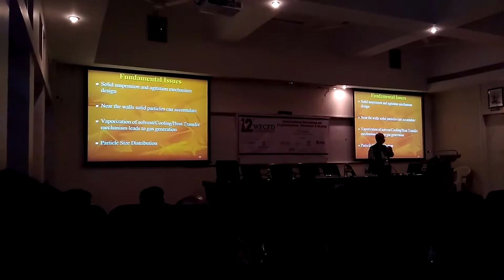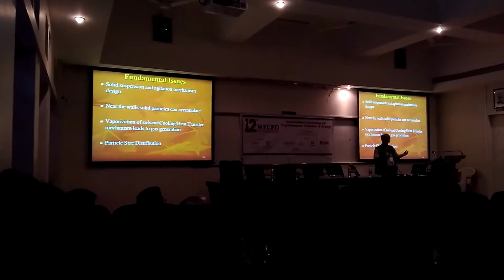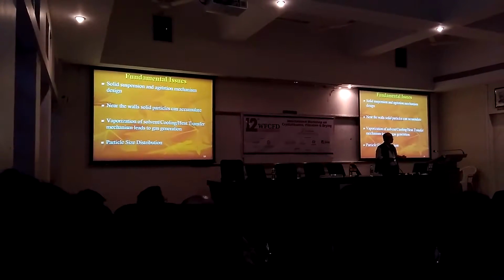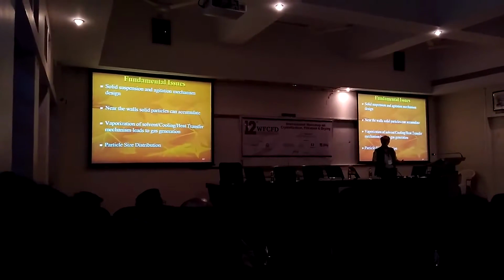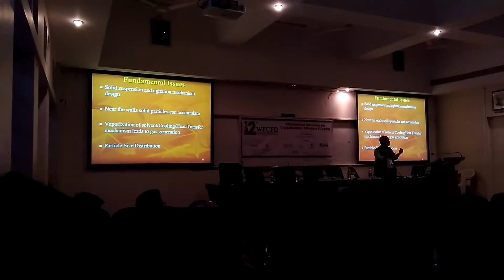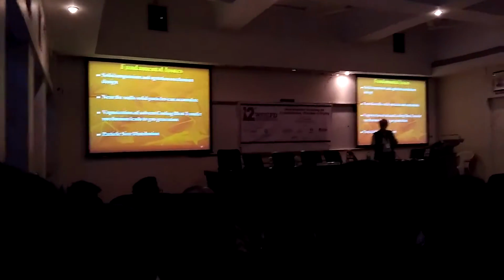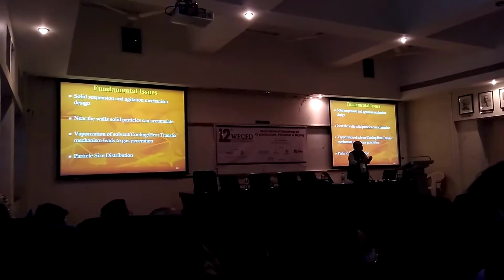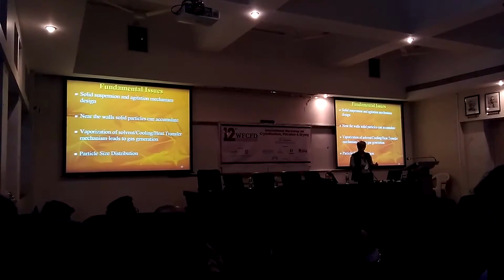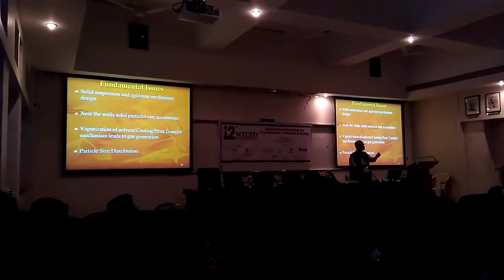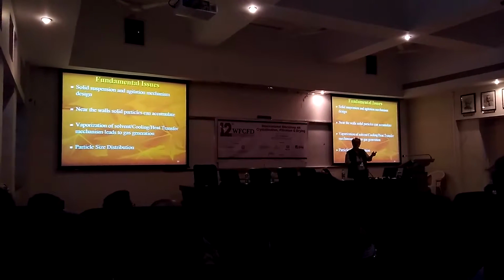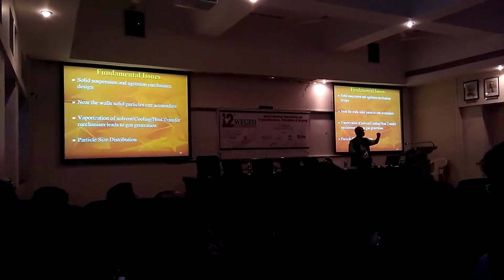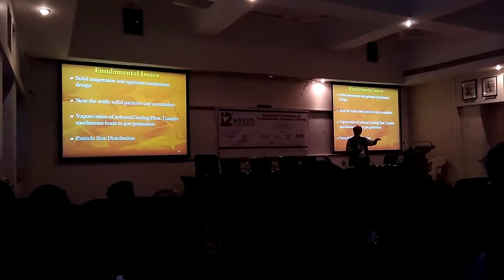Now this is an interesting issue. You design something to keep the solid particles in suspension and then something is getting evaporated. Now when you evaporate it, vapor bubbles are going to get formed. So the system transforms itself from a solid liquid system to a gas liquid solid system, as a result of which the impeller power consumption significantly changes. So whatever impeller speed you had chosen to keep the solid particles in suspension, you may have to increase that particular impeller speed because the density of your mixture is lower due to the presence of vapor.